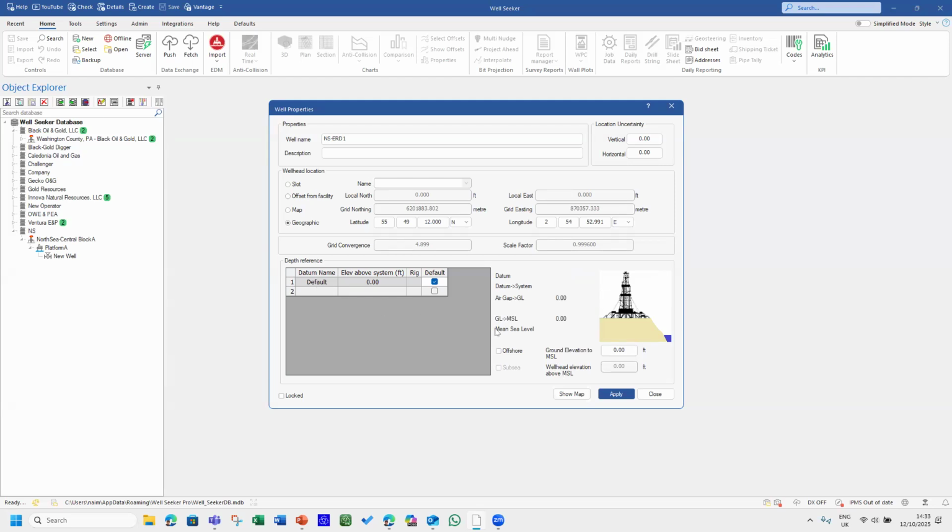Okay, so let's put in air gap, RTE, rotary table elevation. Okay, just a name. It could be any name. You can have the rig name, say rig name RTE. And then you say default, and you would like it to be 150. Suppose it's 150 above the water table. And now you need to tell it what the water depth is. You say water 200.